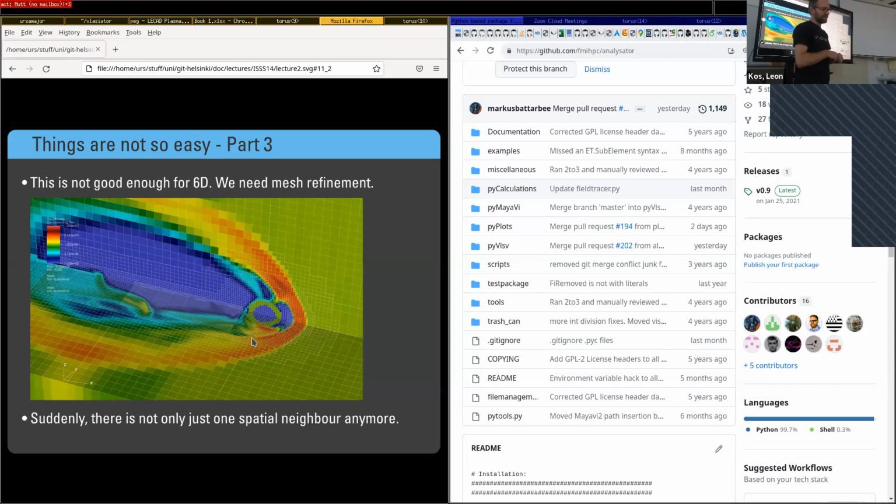So the simplest way of load balancing is, assume your code can do checkpointing and can load the checkpoint with a different domain decomposition. Assume you have this capability. Then the simplest way is to write a checkpoint, stop your simulation, restart your simulation with another domain decomposition, and load all the data you need. That's what is in my head for the serial workflow. We haven't tested it for now, but instead of writing it to a file and hitting the bottleneck, it is possible to use the transport layers of ADIOS to stream your data to yourself.